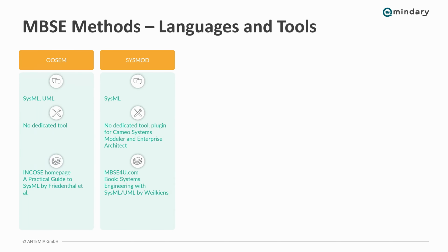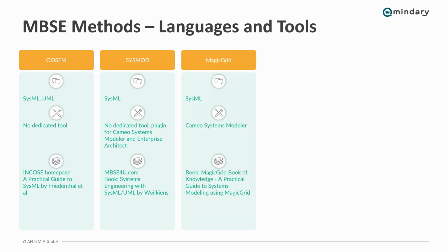SysMod is also another SysML-based MBSE method, also, as we said before, tool independent. SysMod requires to extend SysML with some stereotypes. This can be done with a profiling mechanism of SysML and is in general often done like the tailoring to the specific needs. There are also plugins available that include already the SysML extensions.